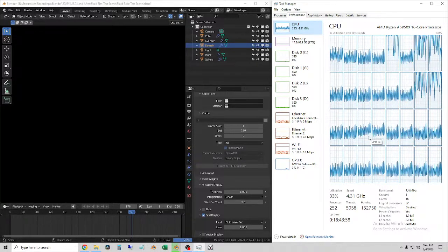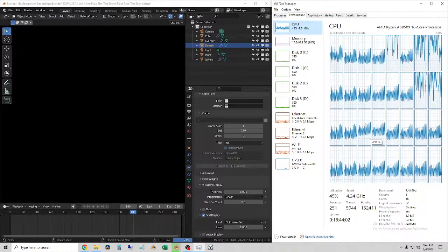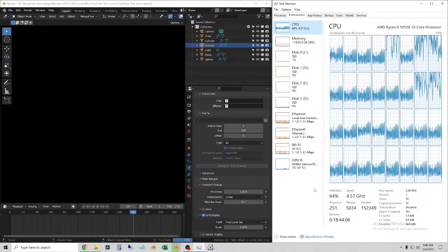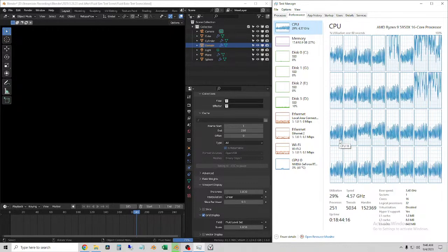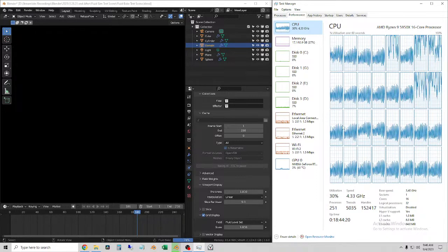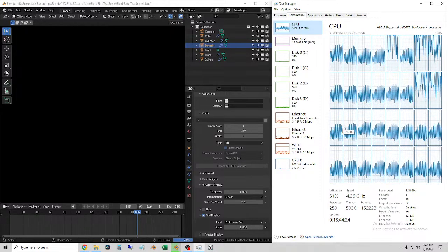The usage graphs on the threads are going to bounce up and down no matter what, because the simulator has to load. Each thread gets basically so many of the voxels, and once it calculates the information for that frame, it dumps it back to the bake file, and then it has to load a new one. So you see this in and out.